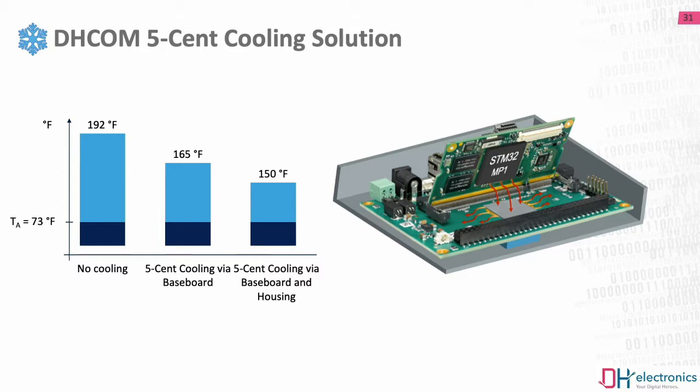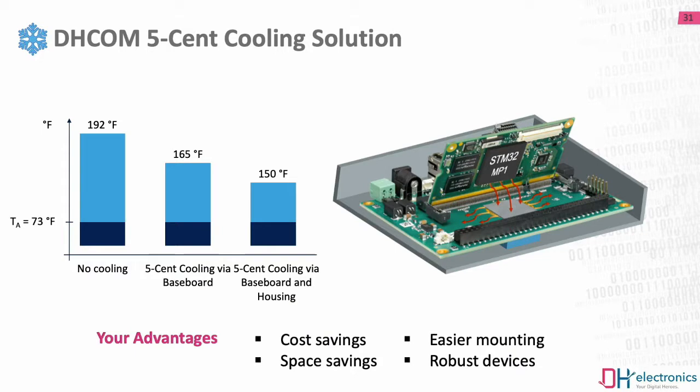So in summary, it can be said you can reduce the heat of the MP1 in this example by 42 degrees only by adding 2 simple gap pads to your design. So this is a cost-saving solution which really extends the lifetime of the chip.